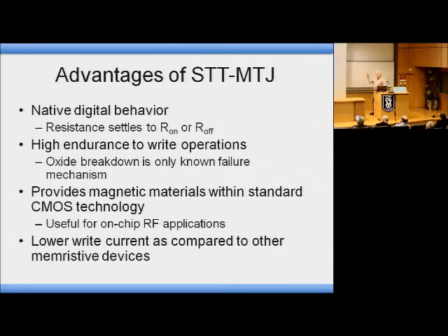The other thing that's kind of neat, and there's lots of applications where magnetism is interesting, is now you're actually integrating a magnetic material onto your chip structure, which offers other applications beyond just this memristive structure, like having RF applications and the like. And one of the things we're going to be talking about, examples of our research, is just that case. And it has a fairly lower write current as compared to other memristive devices. It's still a problem. The write speed is a classic issue in memristive circuits. STT is a little bit better. Still bad, but a little bit better.